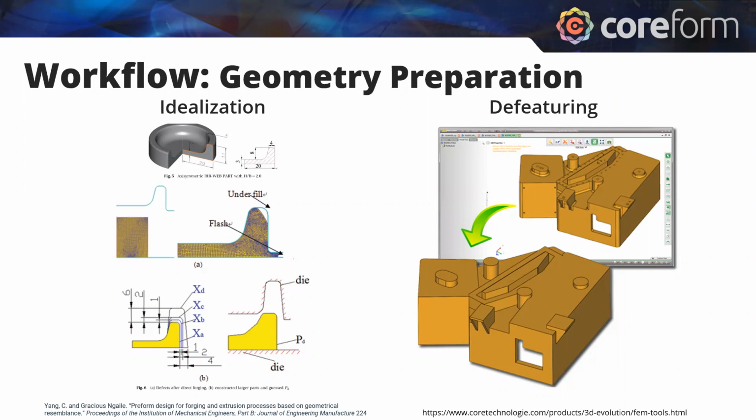Part of defeaturing is just so that you can even build a mesh on a geometry, but also, especially in large assemblies, there are regions you just don't care about. You might have seen, hey, I got a fatigue fracture that occurred in this fillet in this specific part of the body, and I just want to understand the plastic strain increment in that fillet.